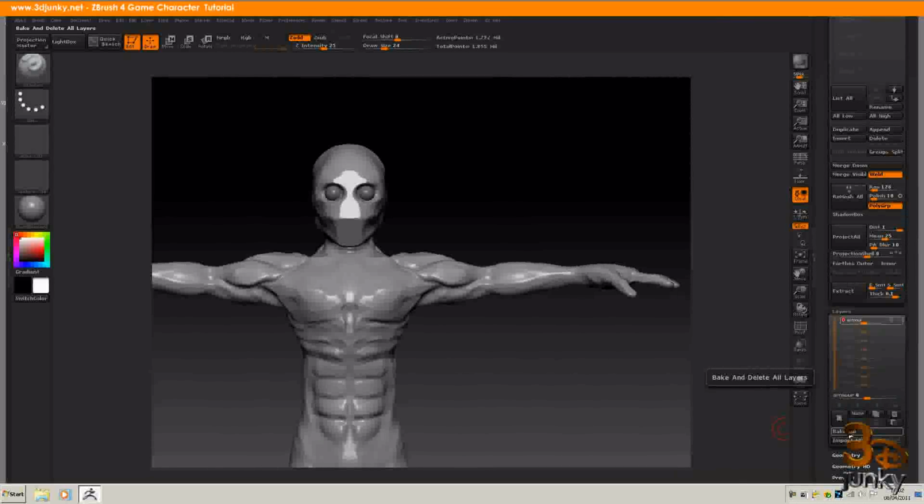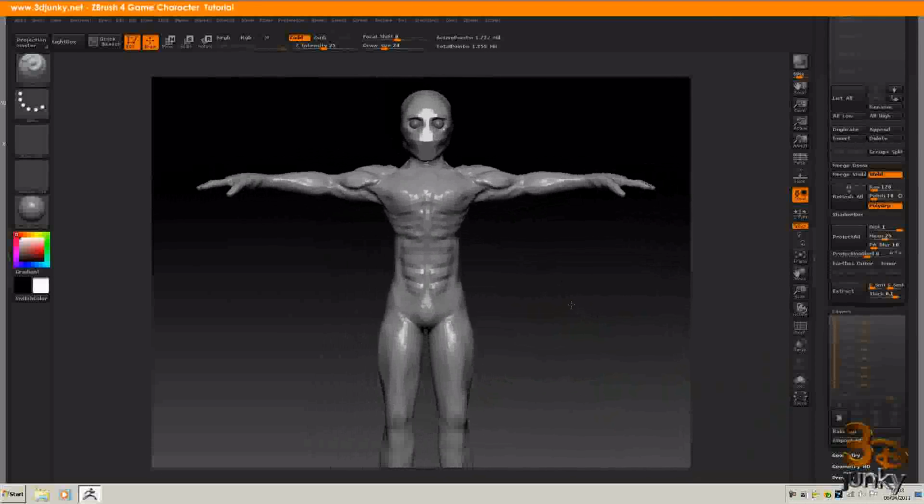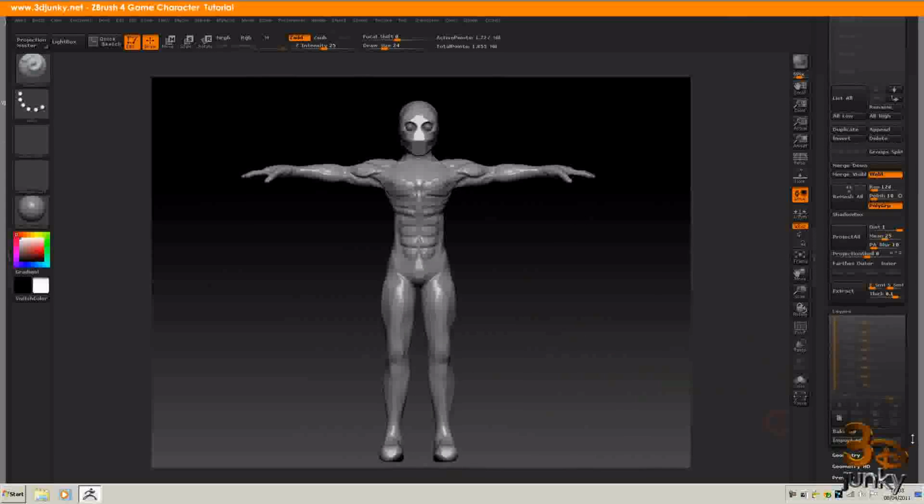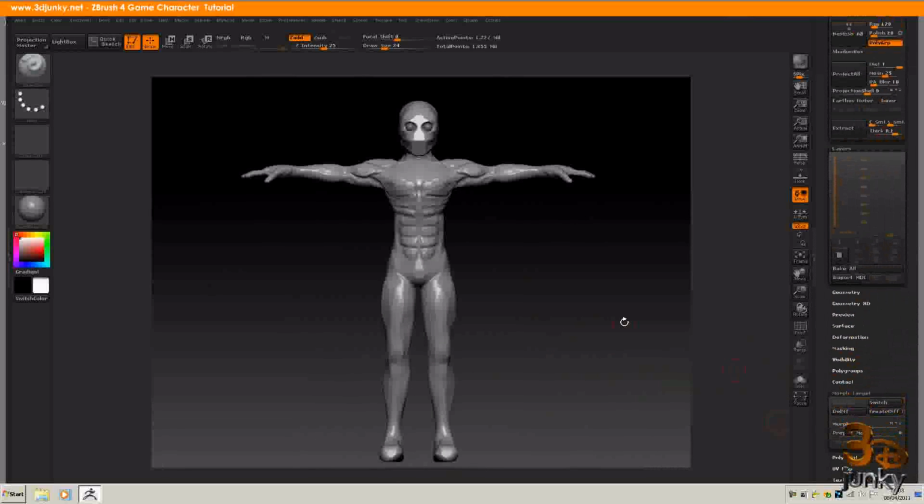I'm just going to bake this back as it is, and then we'll start the process again. So I'll create a new layer. Baking, by the way, will apply it and the layer will disappear. There will be certain options that will not be available while the layer recording mode is turned on. Our morph target has stored this original pattern, and we have it here. We can delete it, we can do it, and that will do pretty much the same thing.